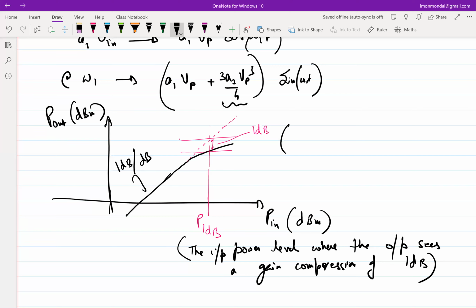Okay, so completing the thought: if I say that my amplifier has a P1 dB of 0 dBm, that doesn't mean that you apply a 0 dBm input and everything will be fine, with no distortion. When you define P1 dB, you are already saying that there is enough distortion to reduce the fundamental gain, which means that to make that amplifier work, you have to apply an input of maybe a couple of dBs below the P1 dB mark. Okay, so that is a typical thumb rule, but how much depends upon how much distortion your spec tolerates.